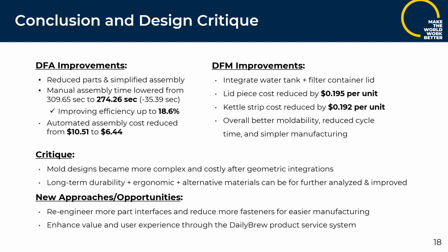In conclusion, our redesign successfully met the goals of simplifying assembly, reducing cost, and improving manufacturability. By reducing the part count and using snap-fit features, the manual assembly time was dropped from 309.65 to 274.26 seconds, and the efficiency was increased from 17.7 to 18.6%. Automated assembly costs also decreased substantially.